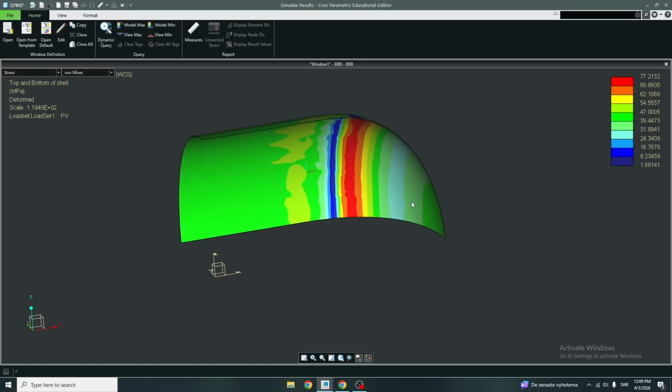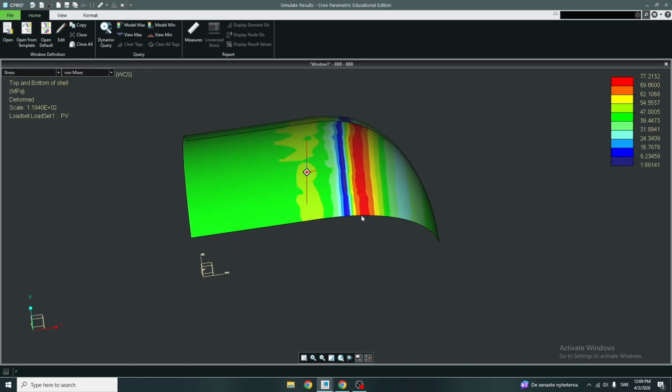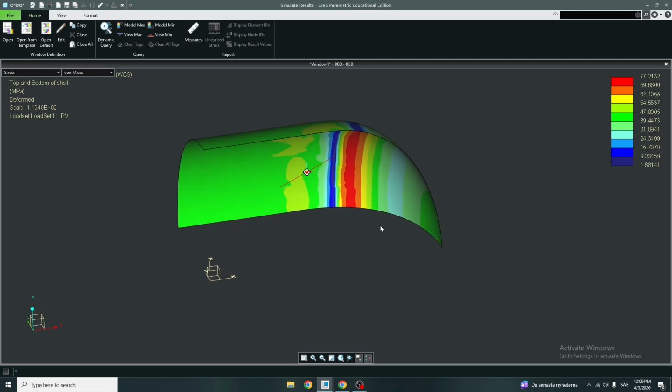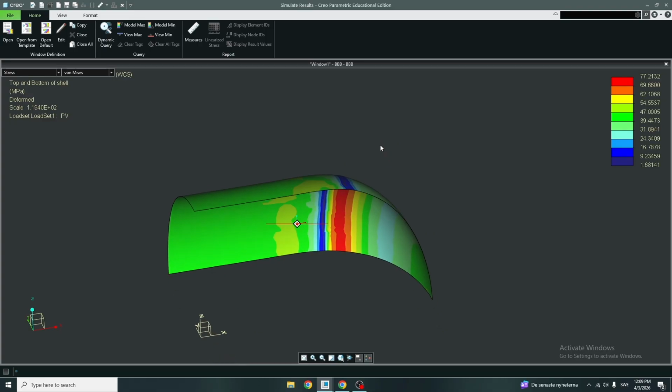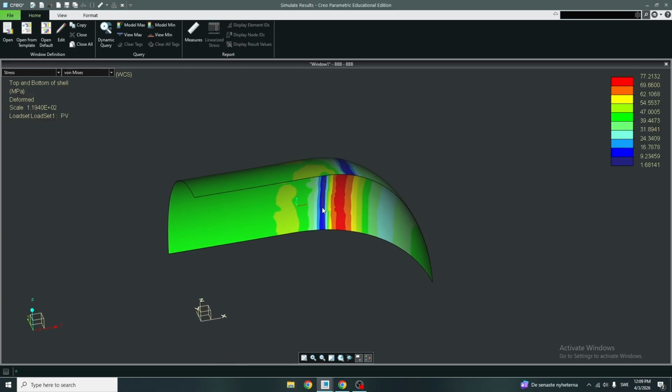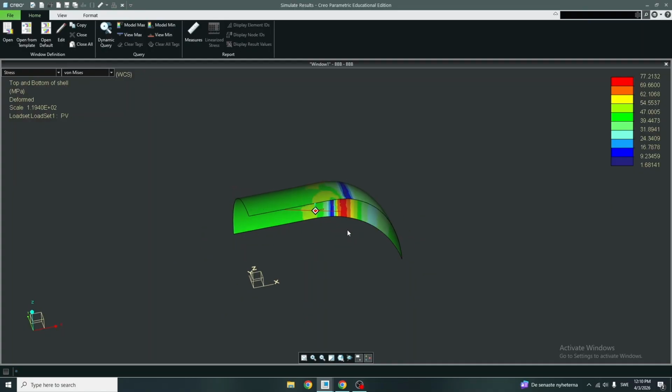Yeah, this is how you calculate the stresses that are introduced when you apply an internal pressure load to a thin-walled cylindrical pressure vessel. If it's a thin wall, we can do it with shell elements. You can use symmetry to your advantage, and you can use the following boundary condition that I have.